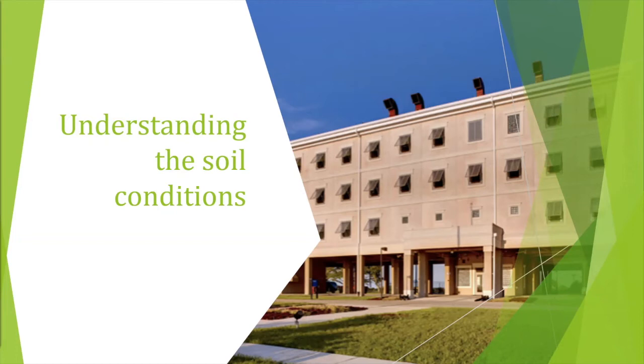We had told them we didn't think the filters were a good idea. We had suggested we needed to do something on the surface a little bit further away, because the high tide water level was much higher than we were told in the report. But again, the contractor bid this all as one, so he went ahead, because technically the underground filters worked. It was very close though.